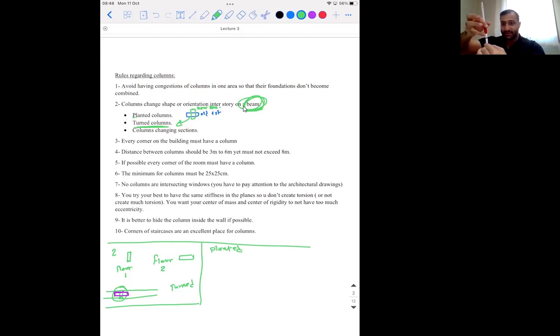But sometimes, like I said, at the periphery of the building, you have this, and then you have a column here starting on the new periphery of the second floor. Now you have a gap between that column and this column. What do you do? You could find a column that's inside and call it a day, right? But what if I don't have something here? There is a solution. It's called the planted column or floating column.